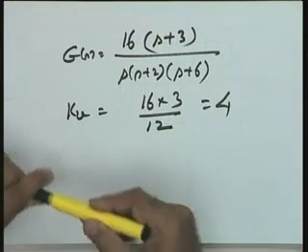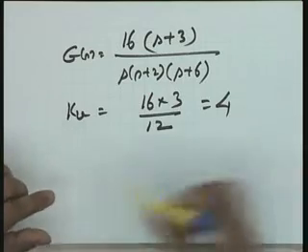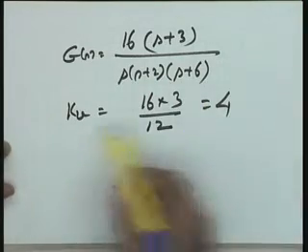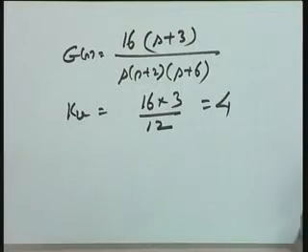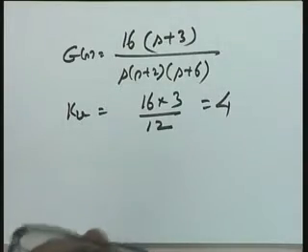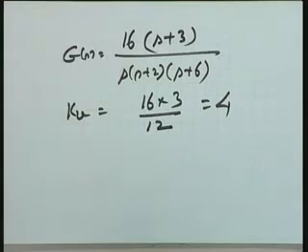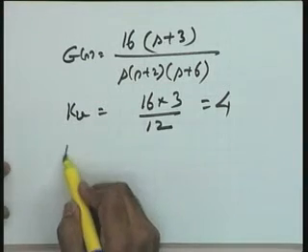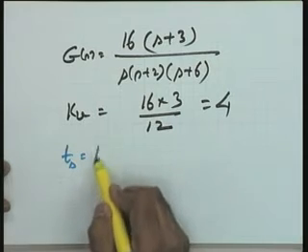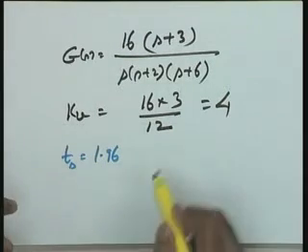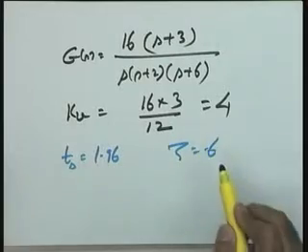Please see that the compensator is changing the Kv also, and this is the relationship you have seen when we add a 0. Now Kv is equal to 4, and the earlier design had Kv equal to 5. Now you have at least reached closer to what the user has said. The user requirements are more or less satisfied. Your Ts is equal to 1.96, and you wanted less than or equal to 4 seconds. Your zeta equal to 0.6, you have already met.